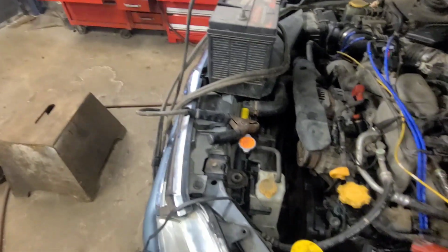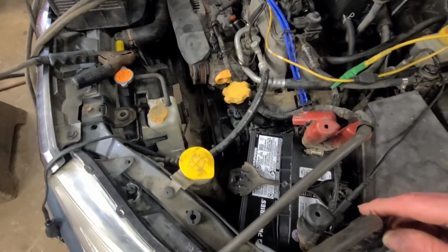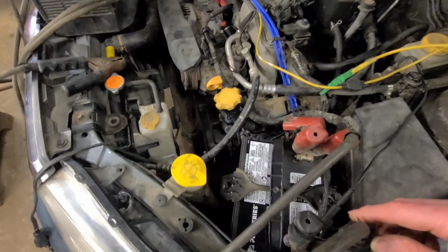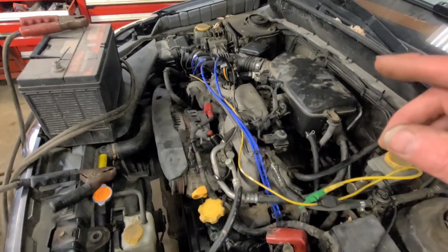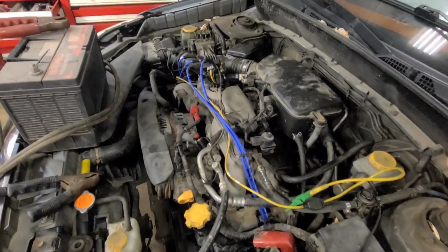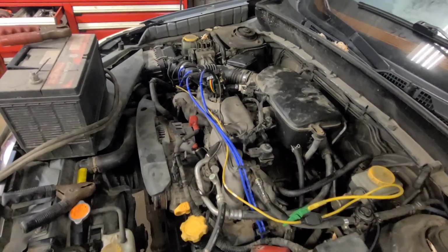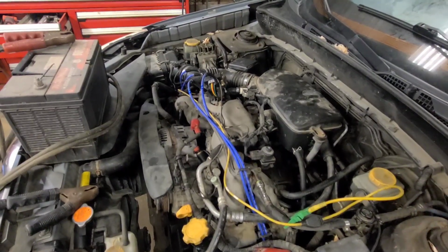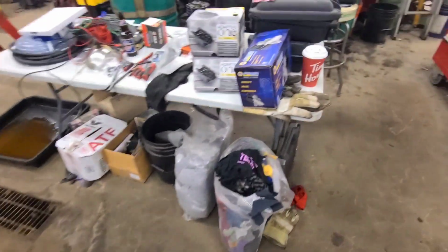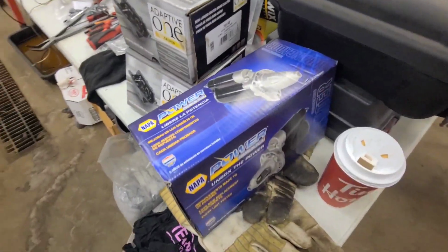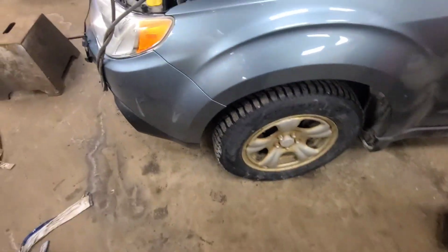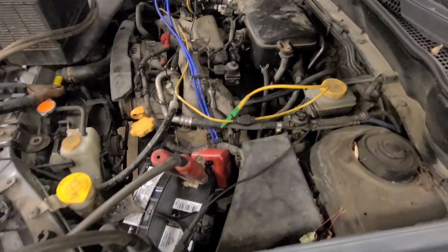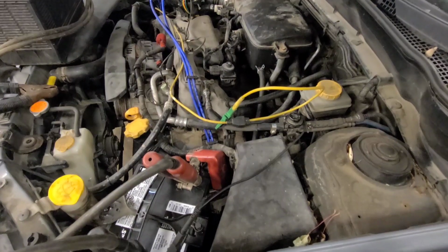I connect the booster cables up to the car, and it cranks just a little bit faster, and it starts. Now I know I've got ignition coil control signals, I've got injector pulse. It seems like that coil is sensitive to RPM. So what I'm going to do is I picked up a reman starter. We're going to change out the starter this evening and see if that helps it crank a little faster, because it does feel a little bit lazy.